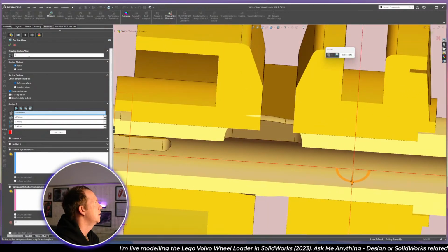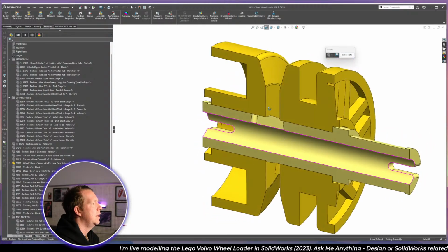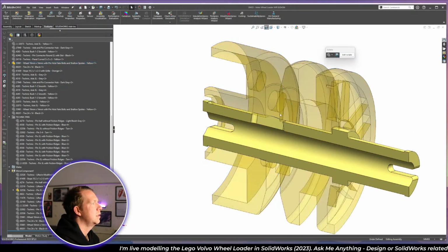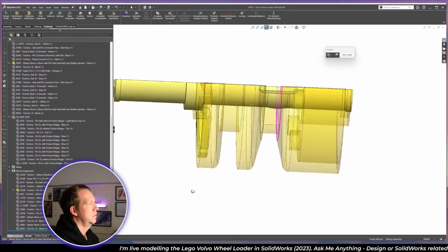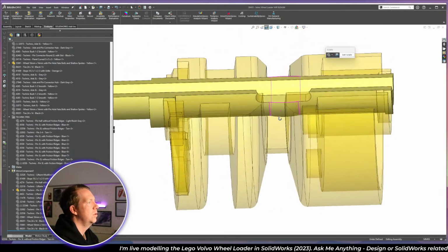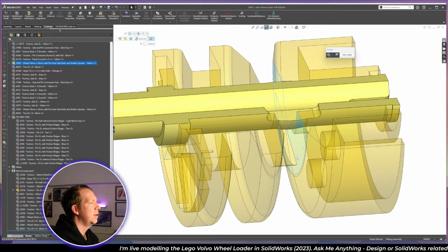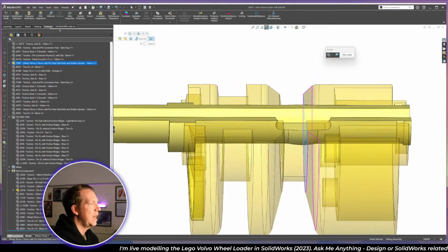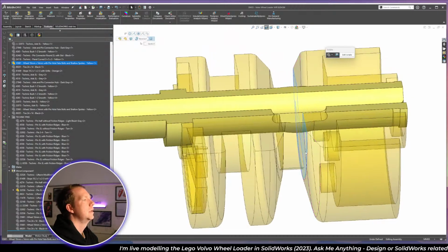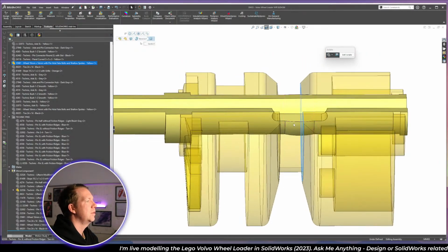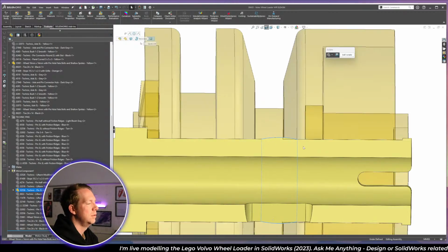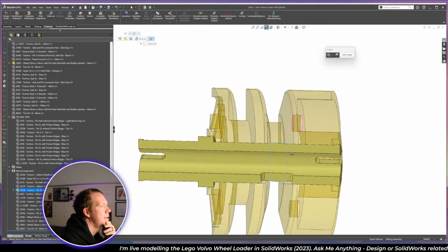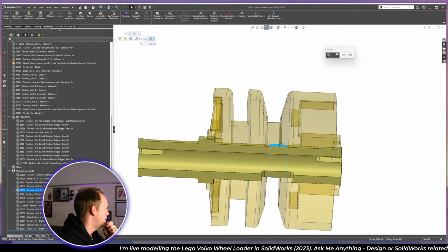And you can see, so this is where there's potential that my measurements are off. High potential, because these are such small measurements and I can't accurately measure the position of this gap. You would expect, looking at the design of these parts, that this thing should sit in the middle. So perhaps the length of this is wrong. Now I can measure that.